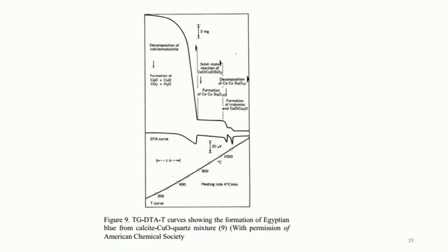Single crystals of calcium, strontium and barium compounds can be grown using borax, lead oxide or sodium carbonate flux with a heating cycle of 30 hours at about 900 degrees Celsius, which we have discussed already.